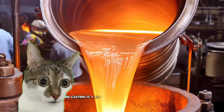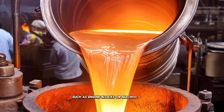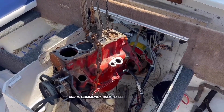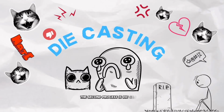Sand casting is best for low to medium production and can produce very large parts, such as engine blocks or machine frames. It is a low-cost process and is commonly used to make engine blocks, pump housings, and large machinery parts. The second process is die casting.